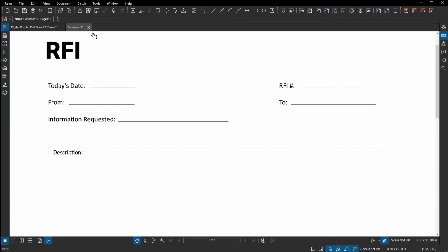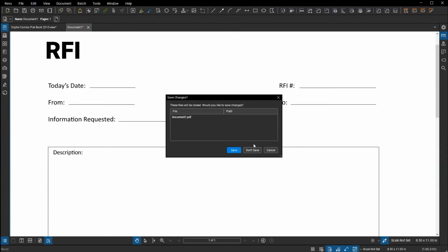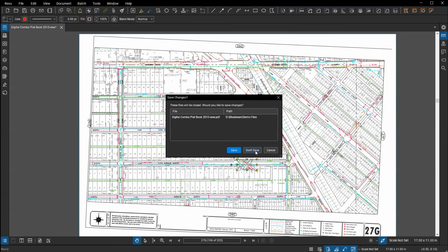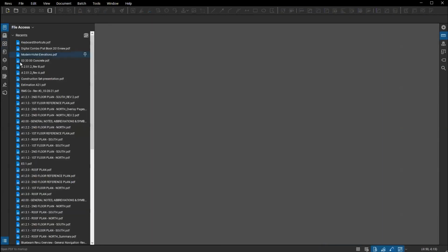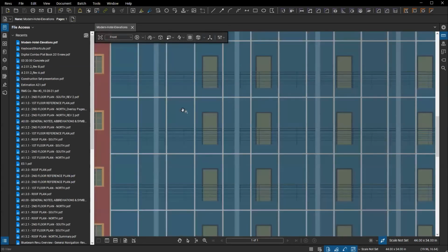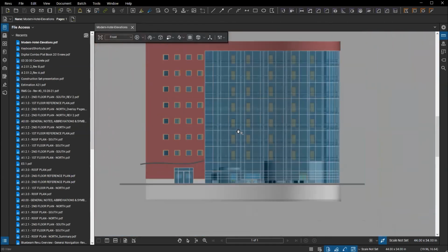And one of the last things I want to hit on, getting down to my last few minutes here, is one of the functions of the software that a lot of folks forget is even available: a 3D PDF. You can make a 3D PDF as long as you have Bluebeam Revu CAD or eXtreme. So you can make a 3D PDF, say, from Revit or from Navisworks, what have you. There are various packages that have plugins that you can make a 3D PDF from. Once you have a 3D PDF created, you don't have to have CAD or eXtreme to look at it. You just have to have that version to create it.